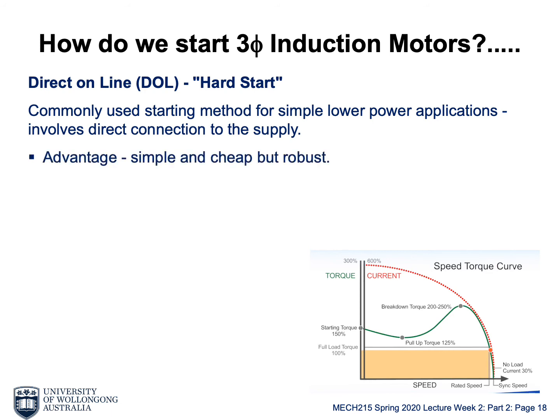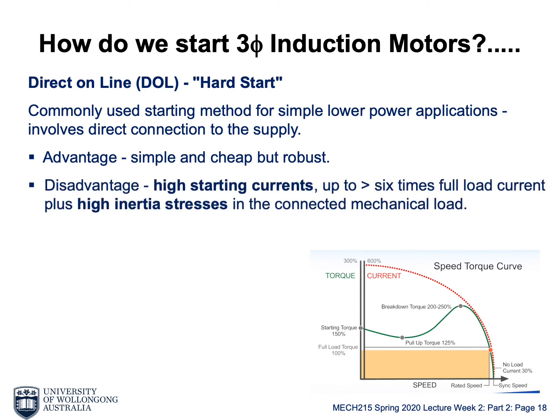The advantage is it's very simple. You don't have to add extra circuits or relays to connect your system, and it's very robust because it's simple. But the problem is there's a large current at the startup period. If your payload is actually high, then the startup period may take too much time, and this long time with high current will generate a lot of heat. So if you follow this red line, your system will follow the red line.